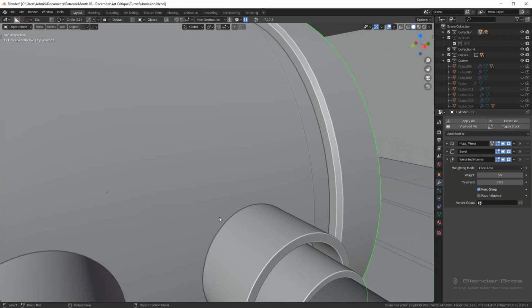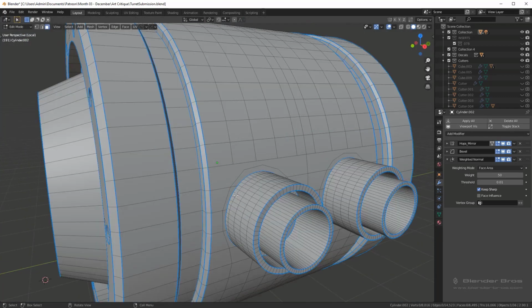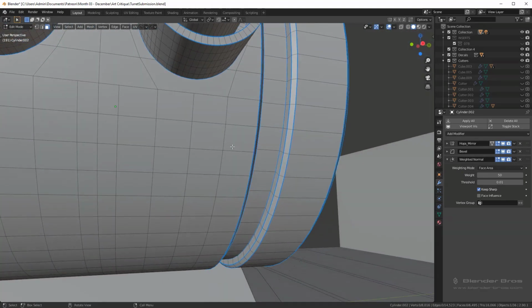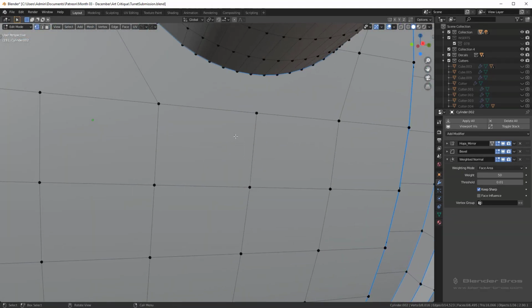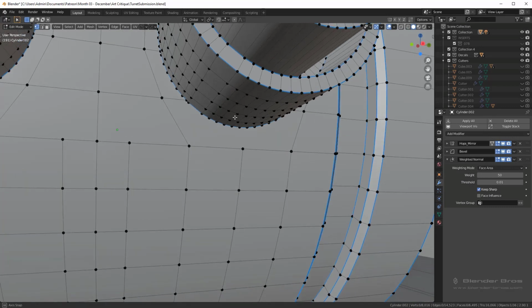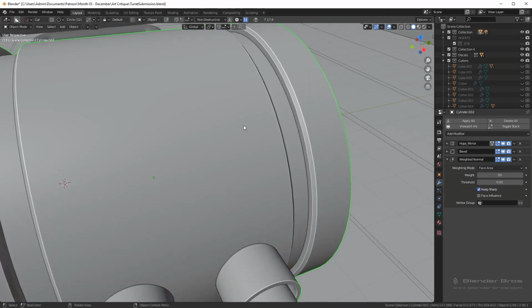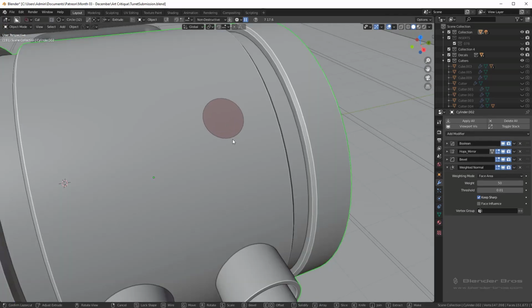And as for these knife cuts you did here, if we go and take a look, I guess it works, but it's not ideal. I would have recommended, instead of doing it this way, keeping your loop cuts flowing through properly, and just have run a boolean instead. You could have used a normal transfer or perhaps just isolated the shading. So next time I would opt for an actual boolean through here, and then you could just do a normal transfer. Let me do it on this one.